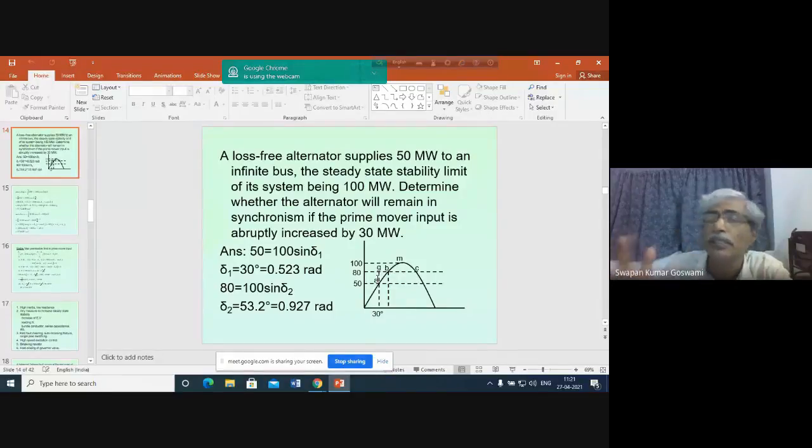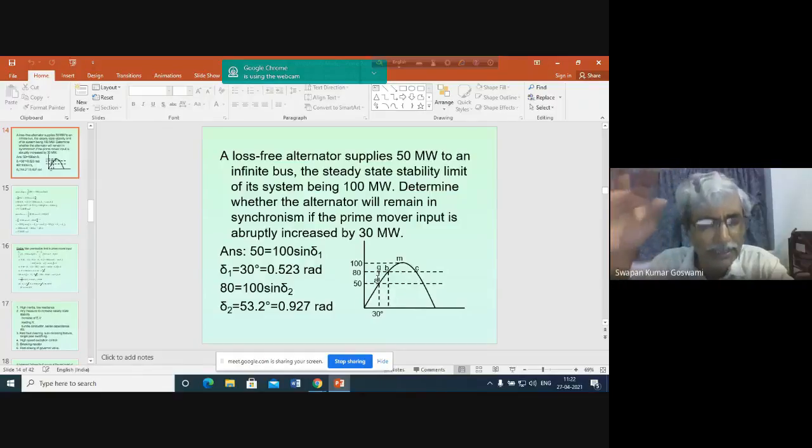So you can say that transient stability does not have a fixed limit. What is the max limit of transient stability? No one can say because there is no such fixed point. There is no such declared stability limit. How much disturbance the generator will be able to withstand depends upon the present operating condition and some other things that we shall be discussing later on.